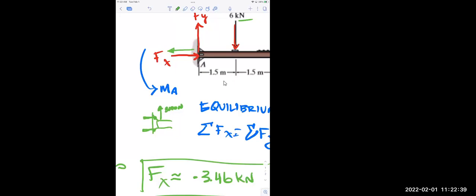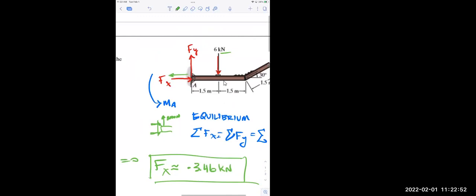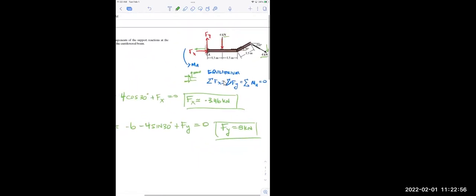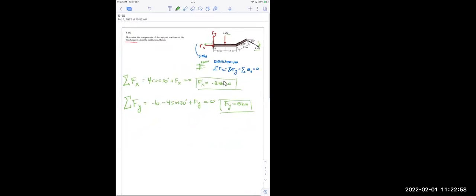How many bolts does it take to avoid 8,000 pounds of shear force on this? It could be 2 really big bolts, could be 4 smaller bolts, but that's something I would need to look up. So anyway, that's interesting. So far I'm able to calc everything in order. It wasn't like I got an equation that had 2 unknowns or something. So this isn't that terrible.